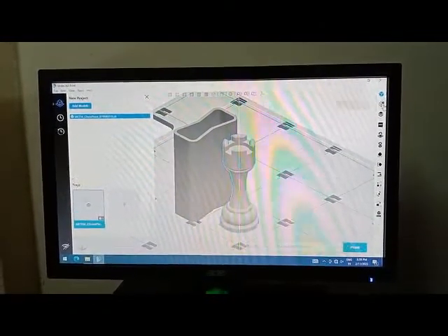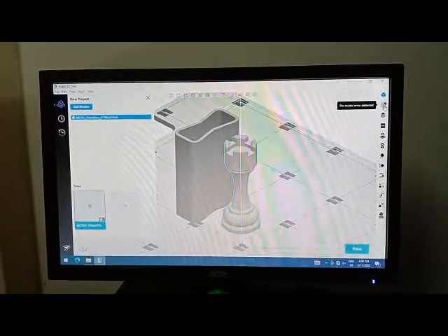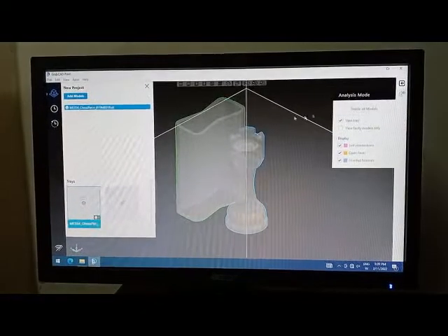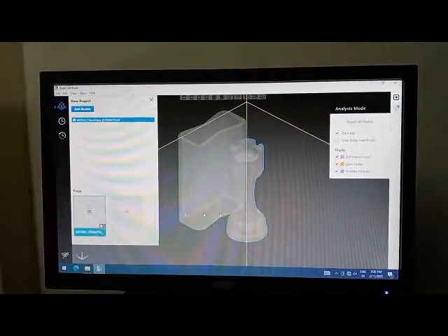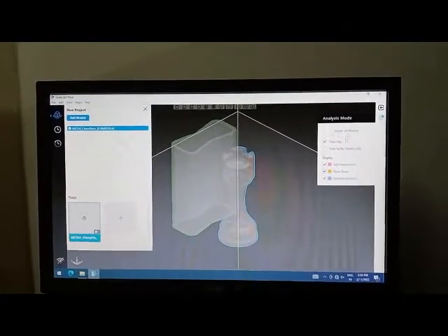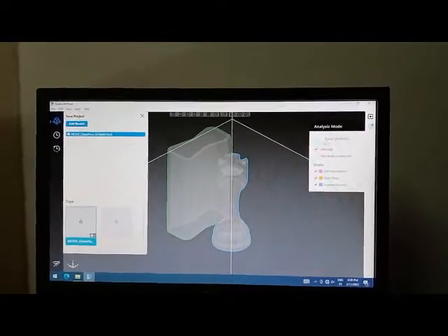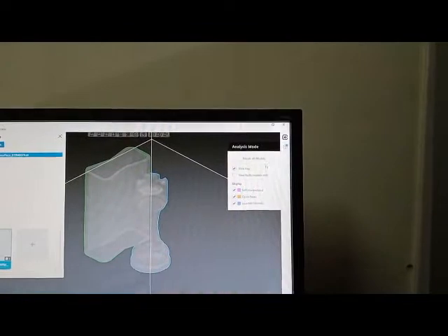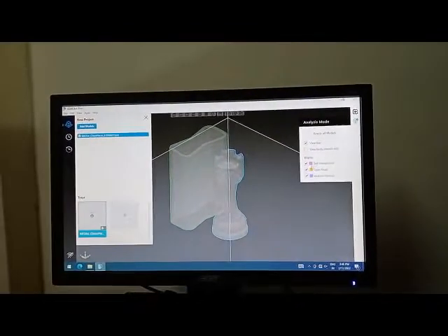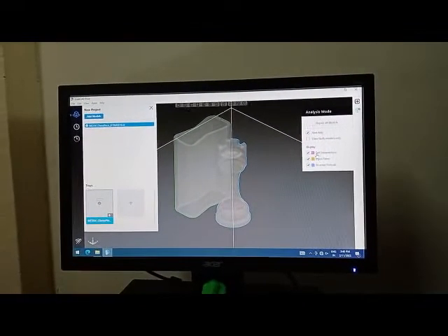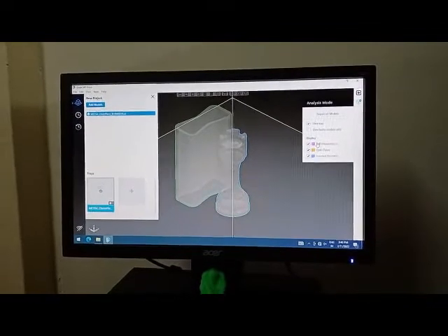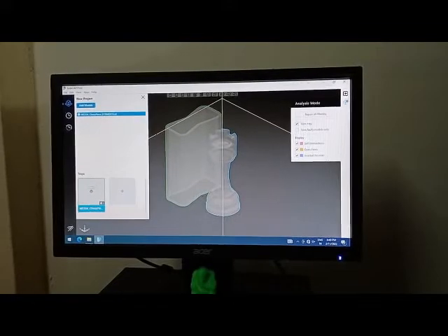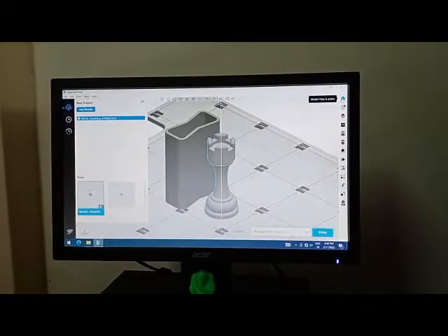What we will do is that first of all we will go for material. If there is any error in the material, we'll just click here, fine. We can see there are no errors in the model, everything is okay. If there are some errors, we can obviously repair them. We have this option, repair all models, fine, and we can view the number of errors. We can have 3 major errors in a model, that is self intersection, open faces and inverted normals. All those things are covered in the first video, fine.